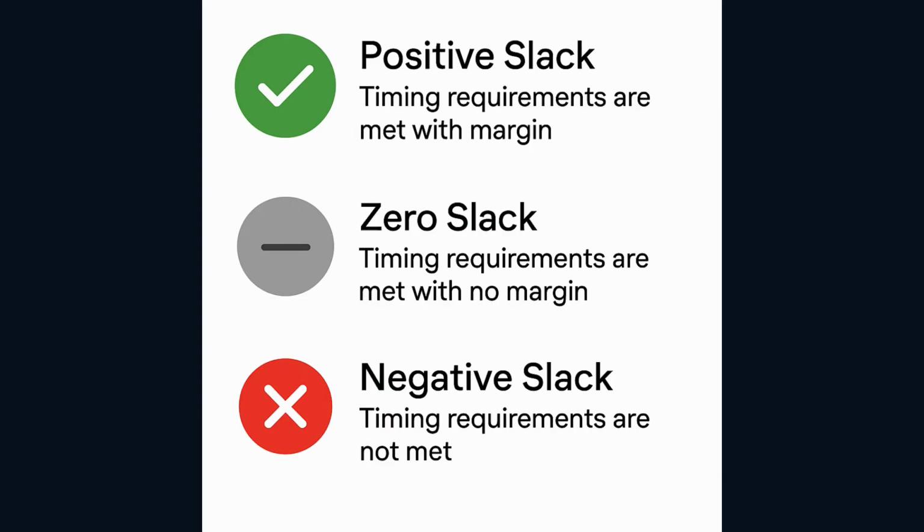What about the opposite? Negative slack. That's the big red flag. It means you have a timing violation. The design is not meeting its timing goals at the target speed. A violation, so it just doesn't work. Pretty much. For a setup violation, negative setup slack, the data isn't getting there fast enough. The chip likely won't function correctly at that speed. You'll get errors, glitches, maybe total failure.